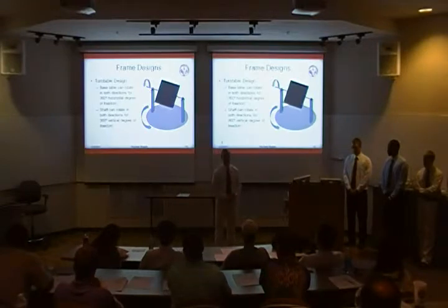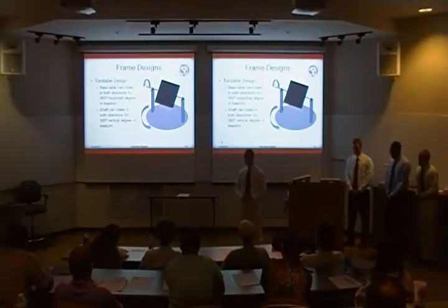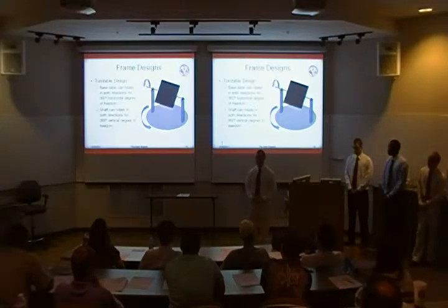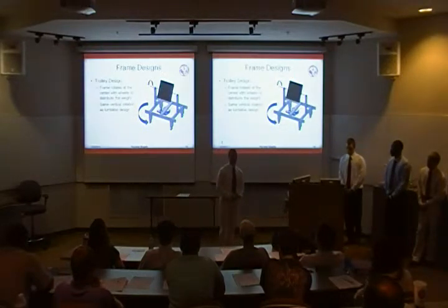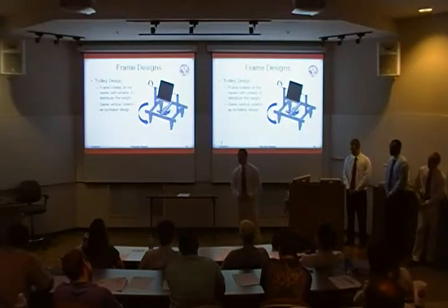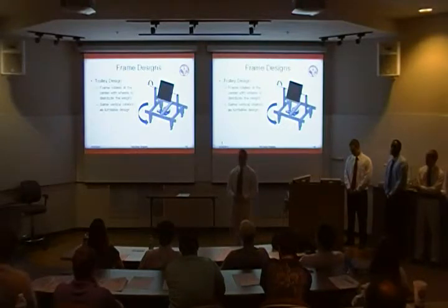This is a preliminary design for a frame. As you can see, it provides 2 degrees of freedom, a horizontal rotational degree of freedom by rotating the base as it rests on a bearing, as well as a vertical rotational degree of freedom as it rotates the shaft upon which the solar panel will sit. We can expand on this frame design by adding wheels to the base of the frame. This will help to distribute weight out across the base of the frame, as well as provide support for our frame and any components resting on it. This should make it easier for our motors to rotate the frame.